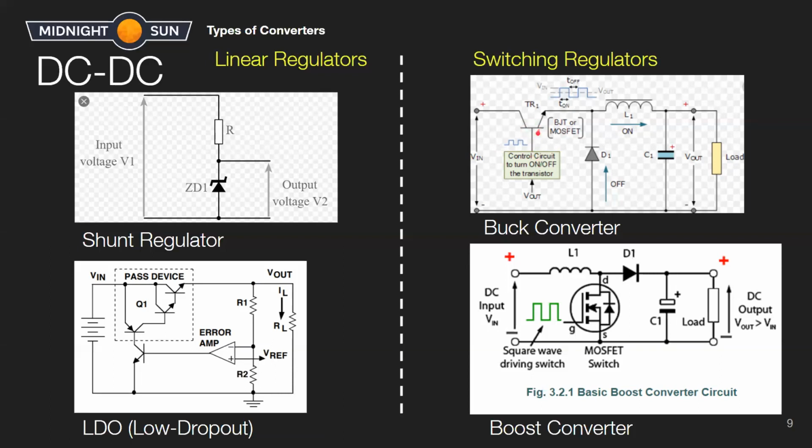What that does is that when the transistor is on, your voltage source is supplying current, completing the path like this. So it's going through the inductor, through the load, and going back around. So you're basically charging our inductor and you're charging our capacitor, just because they're all elements that are part of the circuit when this transistor is on and connected. The way inductors work is that they create a magnetic field, and while you're charging it, this magnetic field is expanding. So we're still getting current going in this direction.